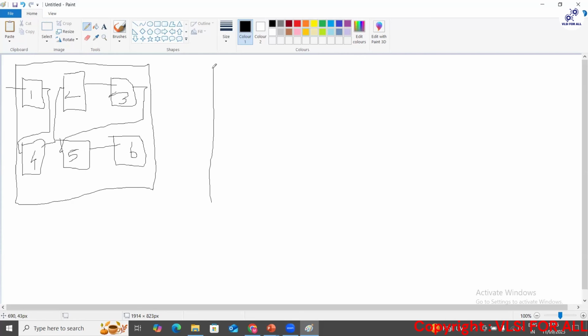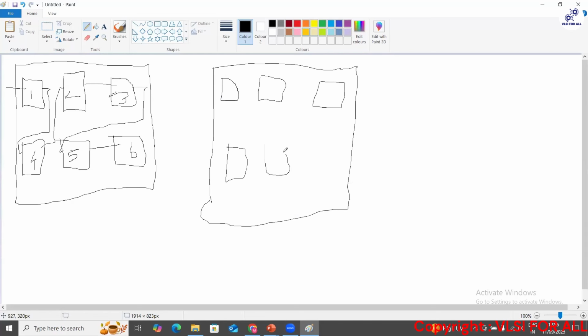So in this scan chain ordering, I'm not altering the location of the flops. I intend to keep this flop like this because I have to meet my functionality. If you talk about two modes, functional mode and scan or debug mode, the main intent of the design is to meet the functionality. Scan is a mode just to test whether the chip is functioning properly or not. So the priority is given to the functional mode.